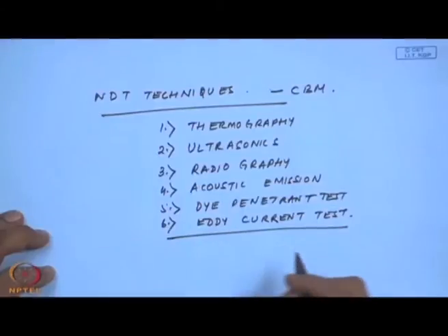If I just recollect, in the whole world about 70% of the CBM techniques are vibration based, followed by 20% being wear debris analysis. And then I was mentioning that a new technique, motor current signature analysis, is also becoming very prevalent, and about another 10%, but out of this 10%, a lot of these are also the NDT techniques.